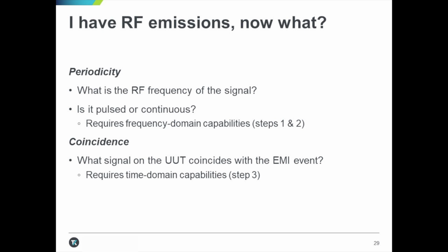They understand how to use near-field probes, but now what? Well, this next step of classifying periodicity and coincidence of each of the emissions of interest helps us to determine, based on the spurious emissions and harmonics that we're seeing, where on our board we need to employ any remediation techniques. This will help tell us where our sources are based on the periodicity and coincidence of the signal that's being either radiated or conducted through an antenna.